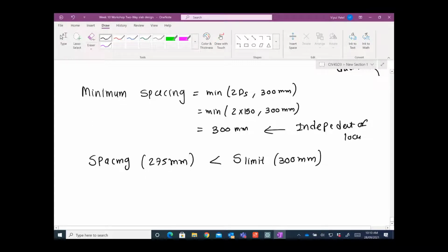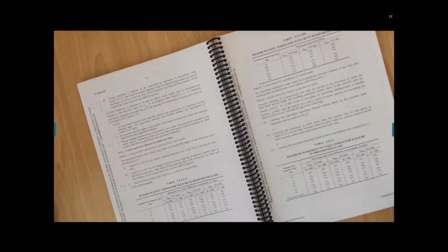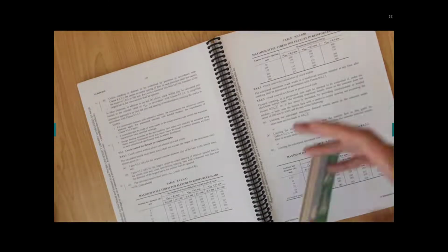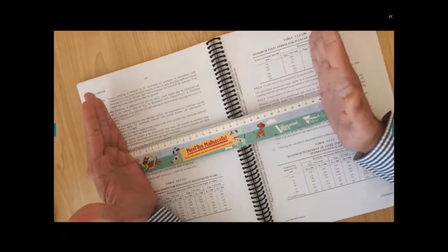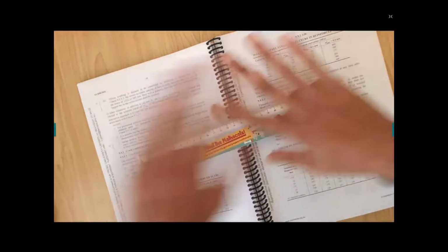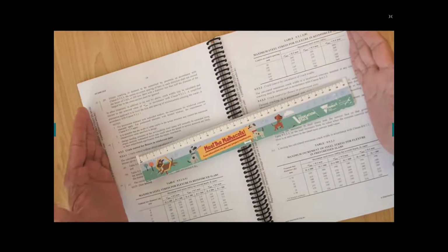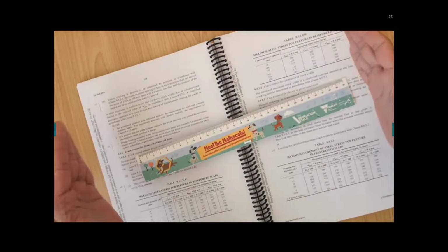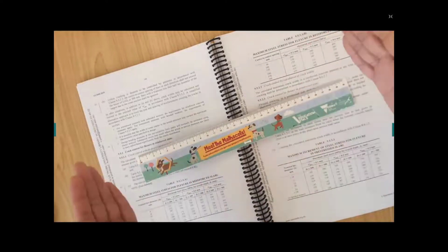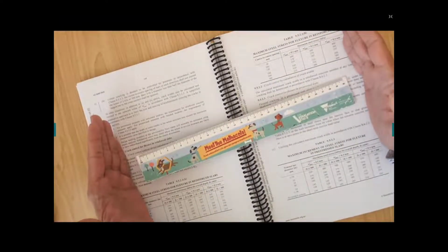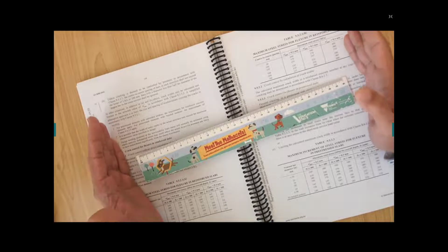So when you design the slab, or if you go to the supervising side, you will see this is the American one, and we follow the American one as well. 300 millimeters means 1 foot. From your first rebar to the second rebar, this is the distance you need to have, regardless of your design. If you tell me you put a 400 millimeter spacing, that is completely wrong. No, there is no way you will have a 400 millimeter spacing of the bar in the slab.